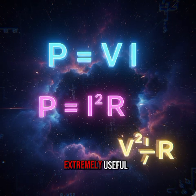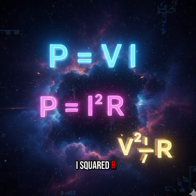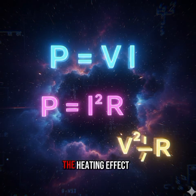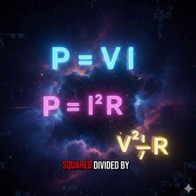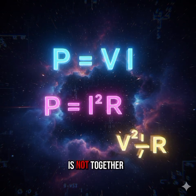These forms are extremely useful. For example, the equation P equals I squared R explains why wires heat up when large currents pass through them. The heating effect depends on the square of the current and the resistance of the wire. Similarly, P equals V squared divided by R is helpful when the voltage is known, but the current is not.